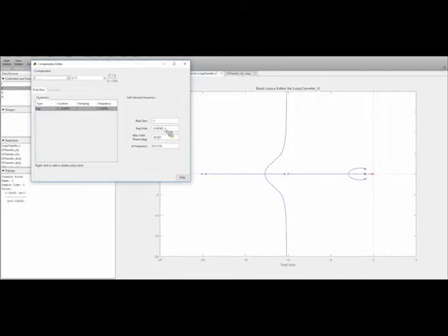I don't know how well we did. We'd have to compare the plots on top of each other, but essentially this does not change the root locus plot any. If I crank up the gain to 22, which is where we said we want it to be, we see a few things that are common from our discussion. We had a pole-zero cancellation here, and another pole-zero cancellation with this pole and the pole from the plant, which is approximately -1. And we had dominant poles here and here. So we've added the lag controller, and basically the same thing is true.